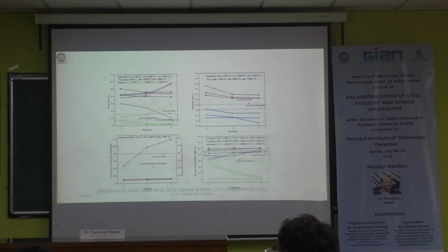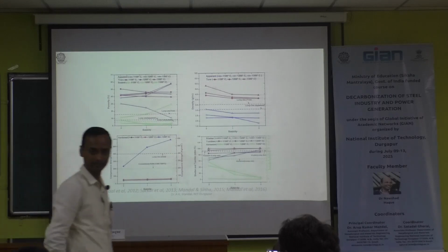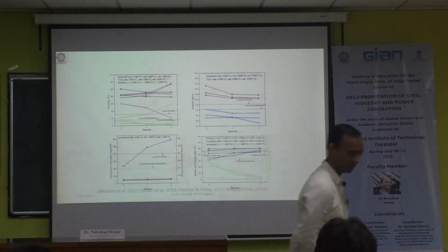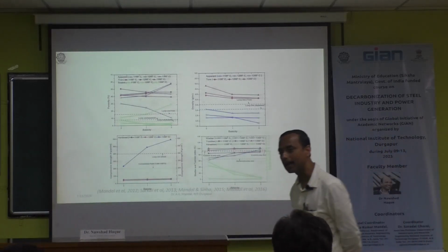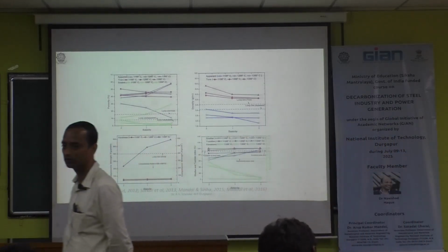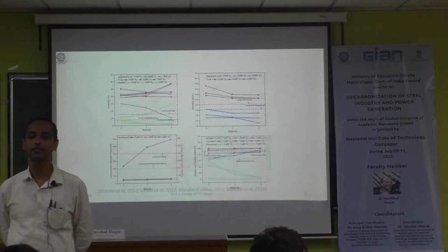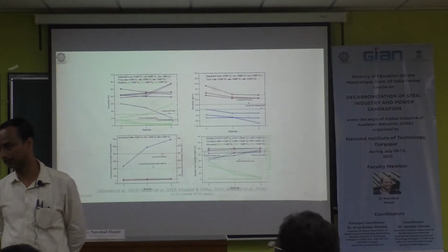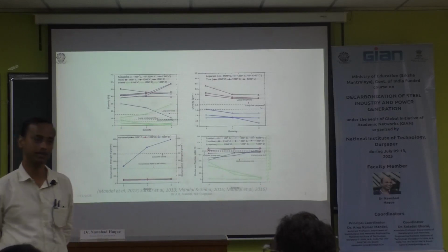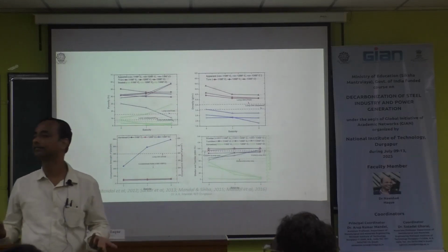Yes. How can you make pellets? Normal green pellet is not so difficult, but the properties at high temperature are. Initially, green pellet formation will be difficult. When you mix that and go for pelletization, what will happen? CaO will react and produce calcium hydroxide. It will generate a lot of heat. Then pellets will break.